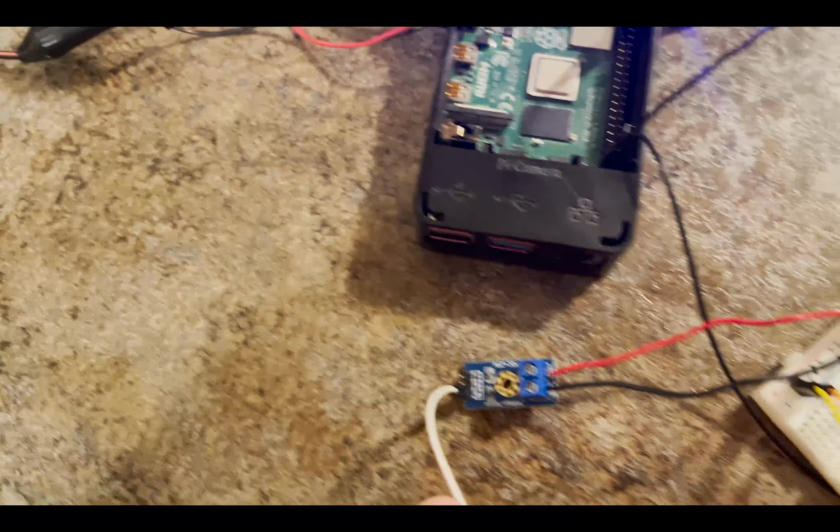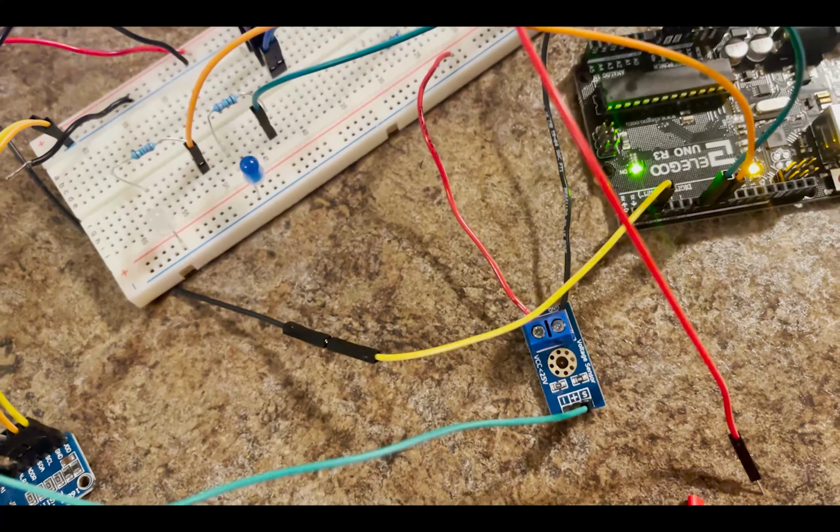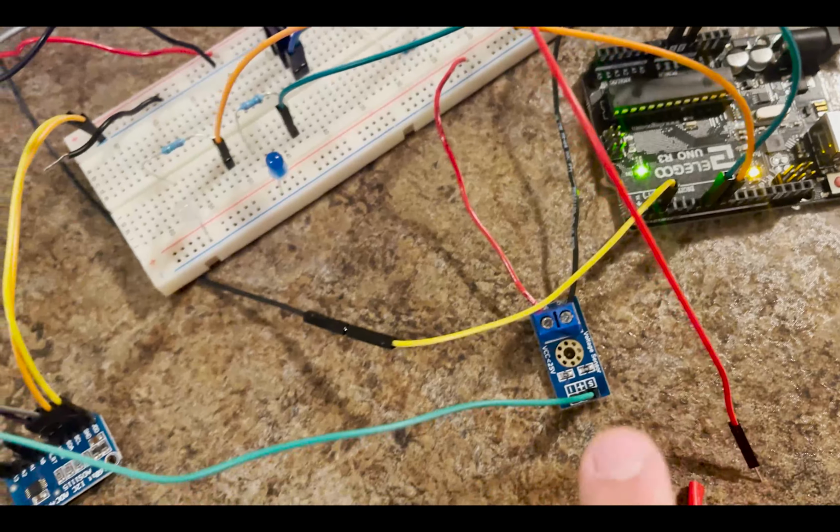And then we have a voltage sensor, and we have another voltage sensor. That just makes it so that we don't put more than 5 volts into the Pi or Arduino. In the Pi's case, it'd actually be 3.3. And then we have the white LED and the blue LED. The white LED will come on, and blue is the interrupt. So I'm going to demonstrate that real quick here.